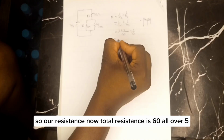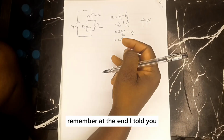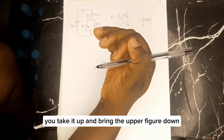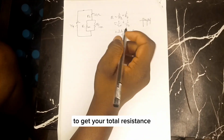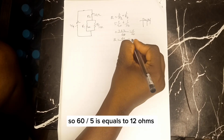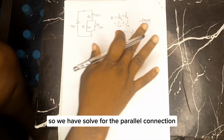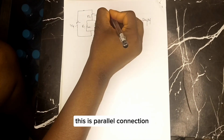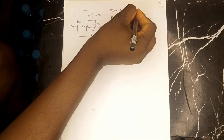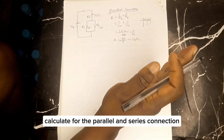So our total resistance now is 60 all over 5. Remember at the end I told you, you take the denominator up and bring the upper figure down to get your total resistance. So 60 divided by 5 is equals to 12 ohms. So we have solved for the parallel connection. This is parallel connection. Remember, they told us to look for parallel and series connection. We should calculate for the parallel and series connection.